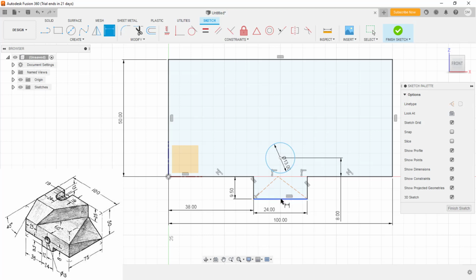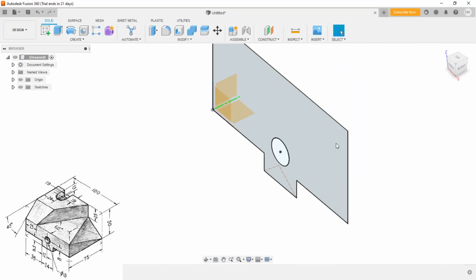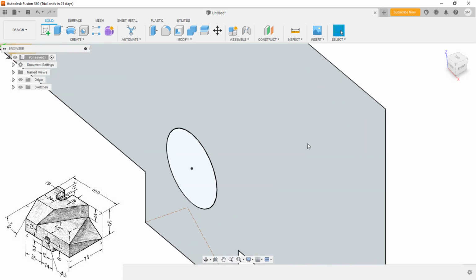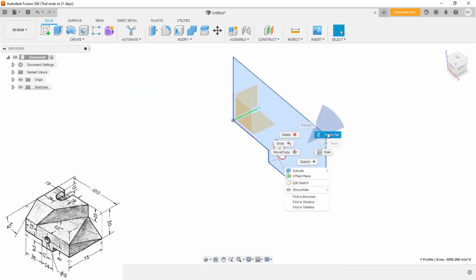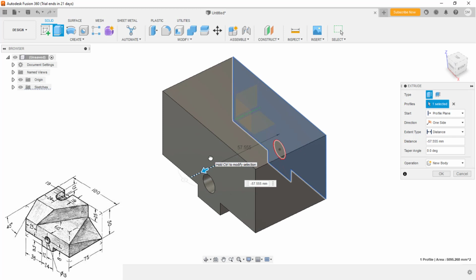Right? Now these, you can snap the midpoints here. So again, we could snap in SolidWorks. It is 12. Yep, so dimensions are fine, fully defined. Finish the sketch, extrude up to 75. So simply right click on it, pull up to 75 or minus 75 is fine.